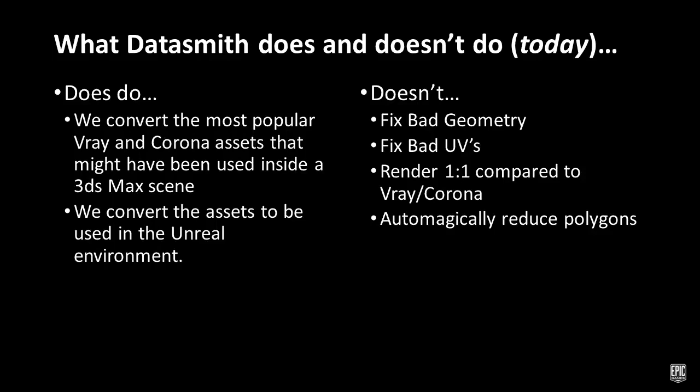Datasmith doesn't fix bad geometry. So you're going to want to make sure that your geometry is well structured and has good surface topology. Really, a lot of the same best practices that you would employ for an offline rendered workflow. You want to avoid open edges where possible.